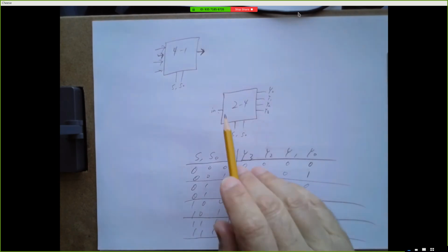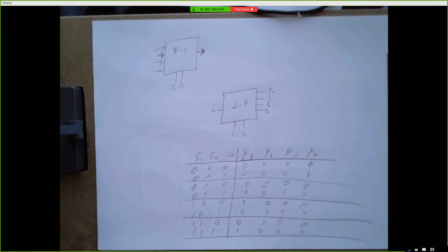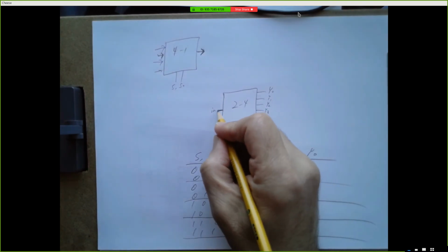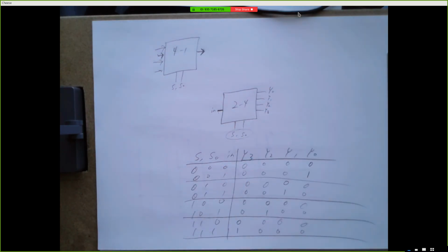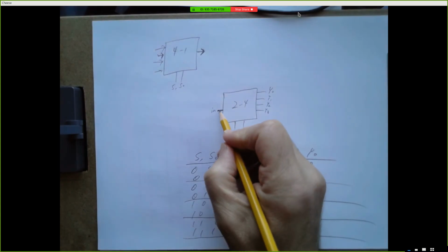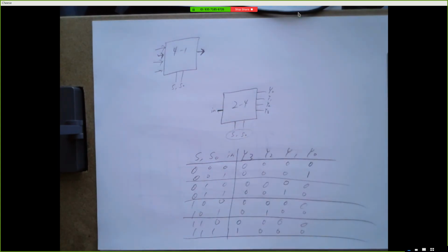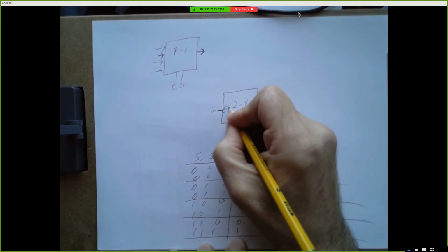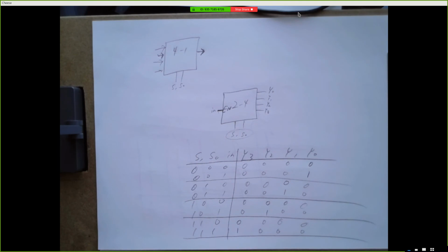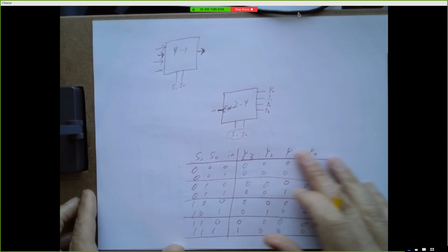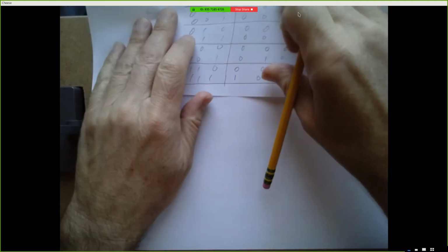One, it's a way to route your input to one of 4 outputs. But you can also look at it as if our input is 1, we can use this circuit to assert one of our 4 outputs. Whereas if our input is 0, we don't assert any of our outputs. So sometimes you see a 2 to 4 demultiplexer written with this input labeled something like EN for enable. And so we could take this truth table and write it more simply as follows.